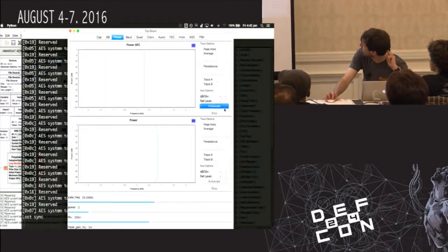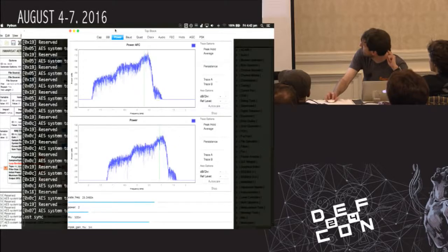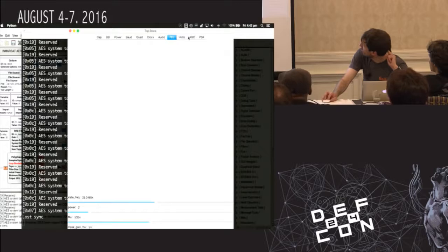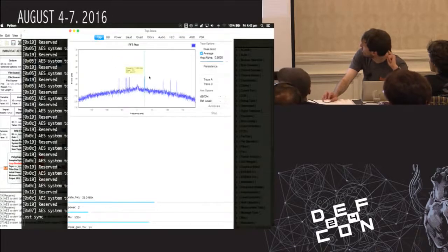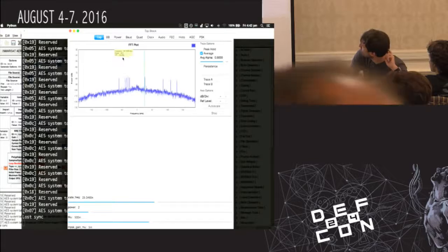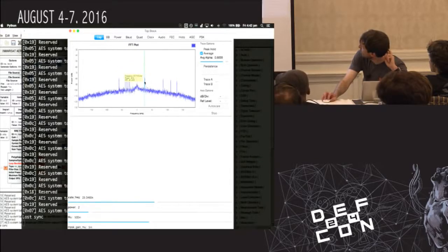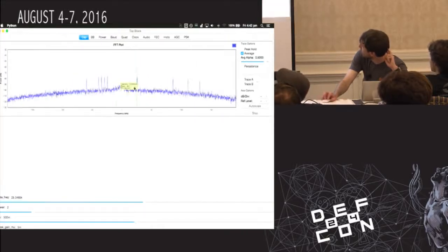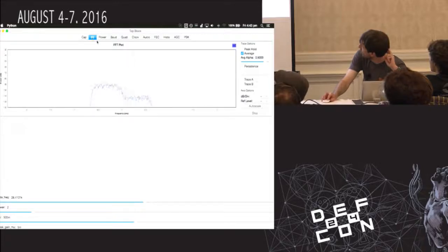Do that power stuff that I was talking about with the squaring and looking for the peaks, looking for the baud rate and so on. So I'll show you this in the newer version. But initially I just thought, well, why not do something like once you actually click on one of these things, the channels are really narrow, so you have to be pretty accurate. But you can't be accurate all the time, so you want it to do some automatic tuning. So if you look here, you see how the green line's tracking over and trying to find the midpoint there.